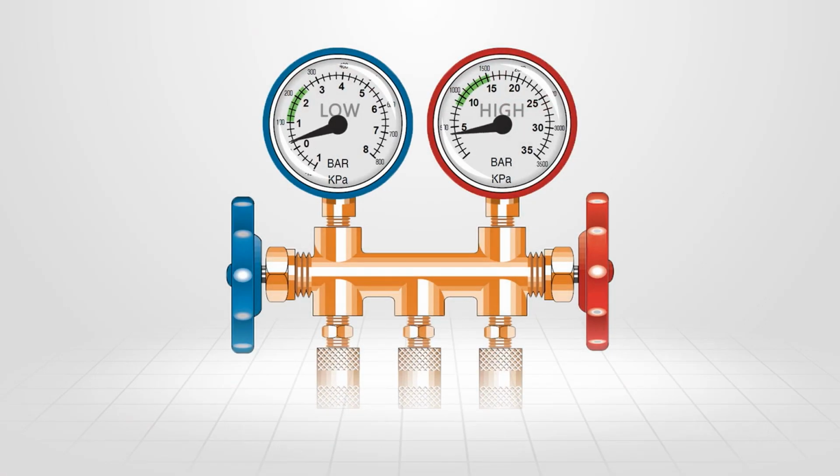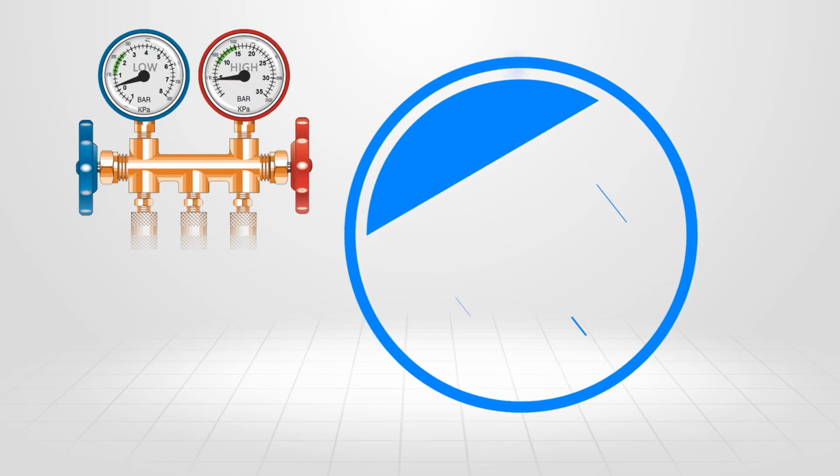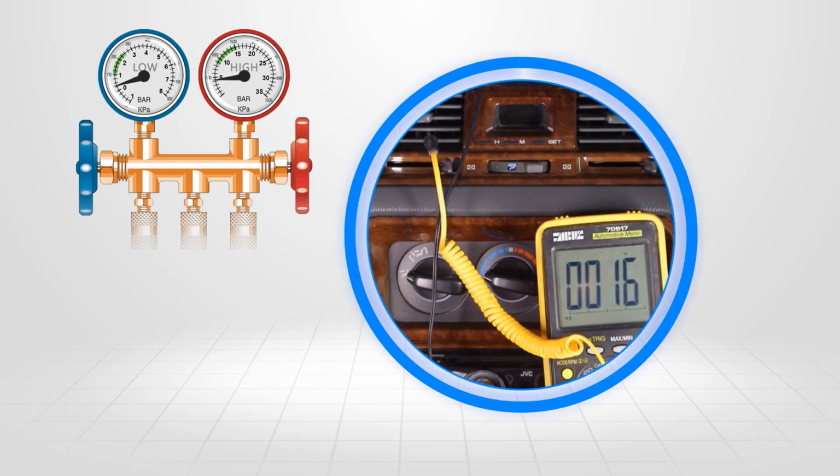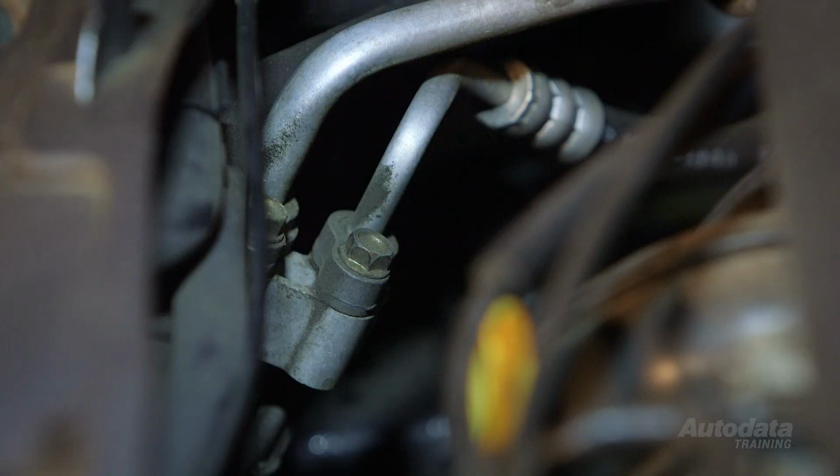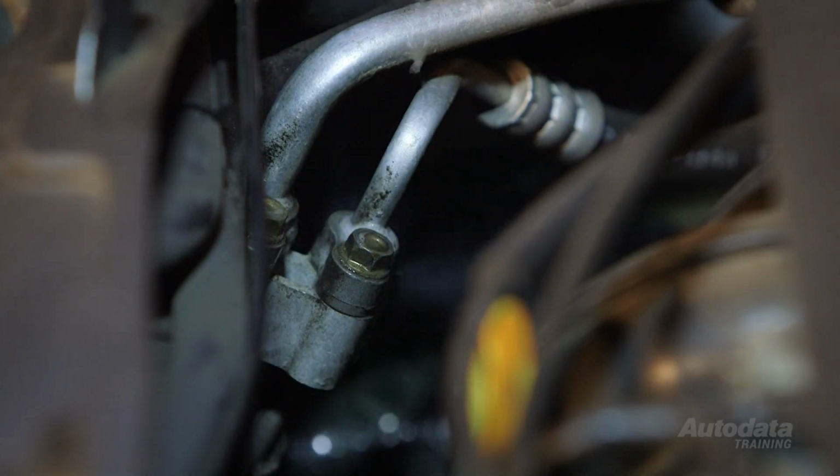With both gauges lower than normal, warm centre vent temperature and complaints of hissing sounds from behind the dash panel, a low refrigerant charge may be the cause. Confirm the compressor is cycling and perform leak diagnosis before recharging the system.